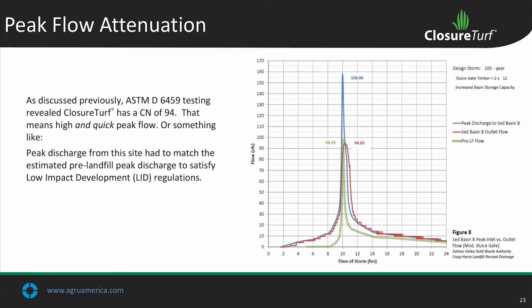So you can drive on it and it'll carry water. You don't have to build a soil section on the bench in order to cut a V-ditch at the upper slope toe, carry all that water away. You can use what you've got out there as far as intermediate soil cover and just cap it with HydroTurf, and you'll have a nice hydraulic system for concentrated flow.